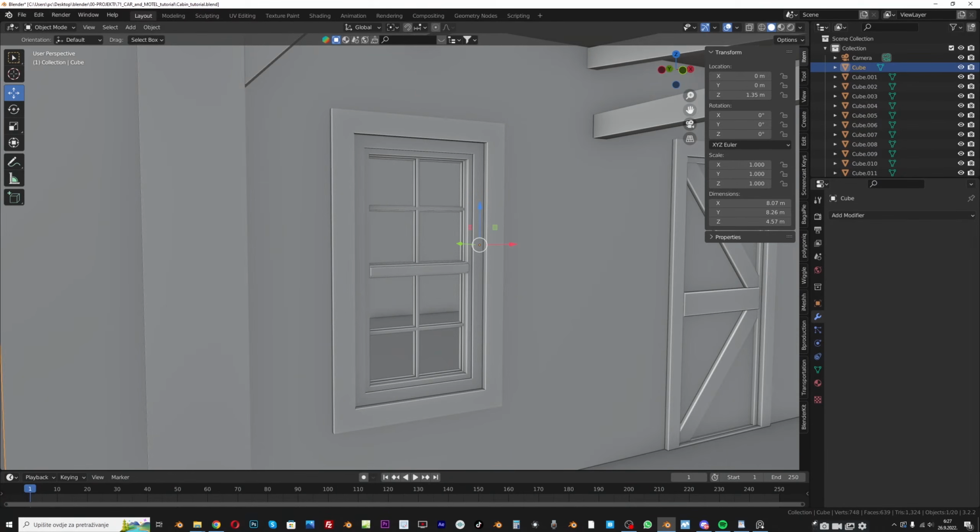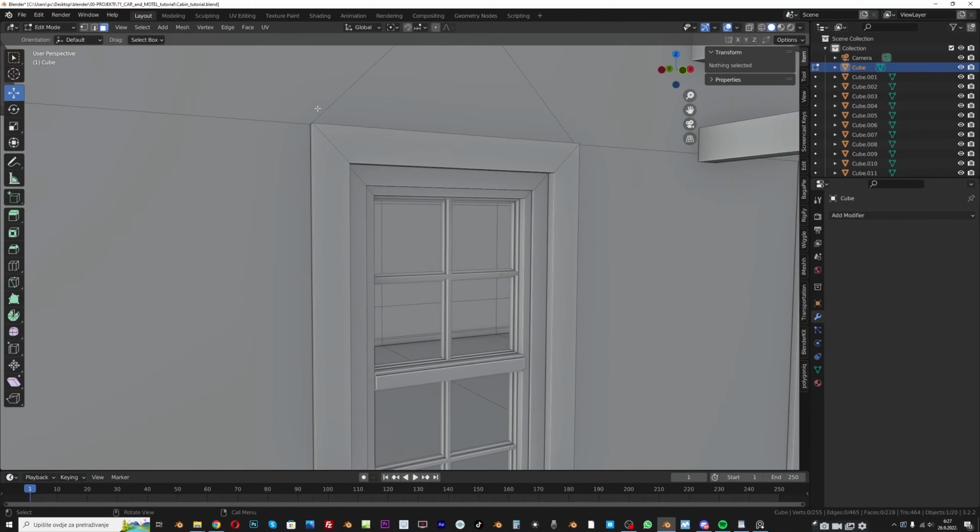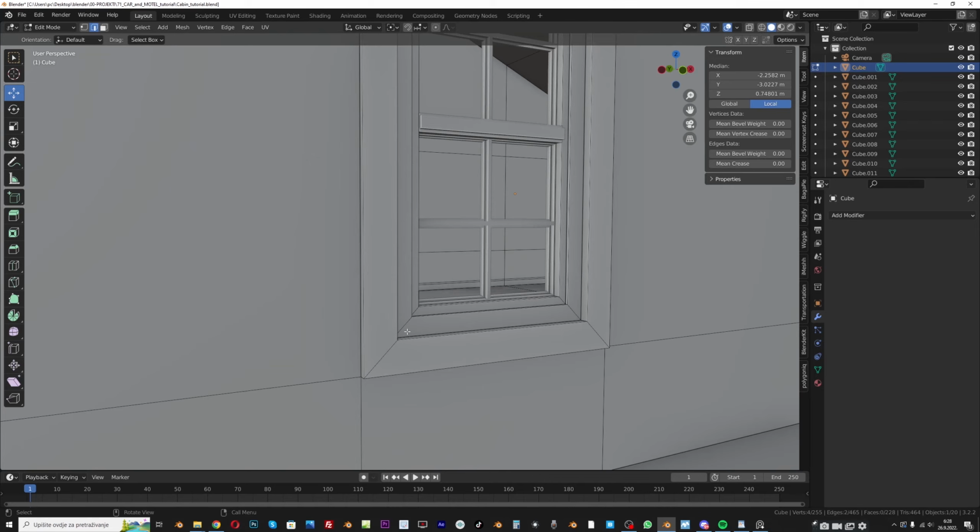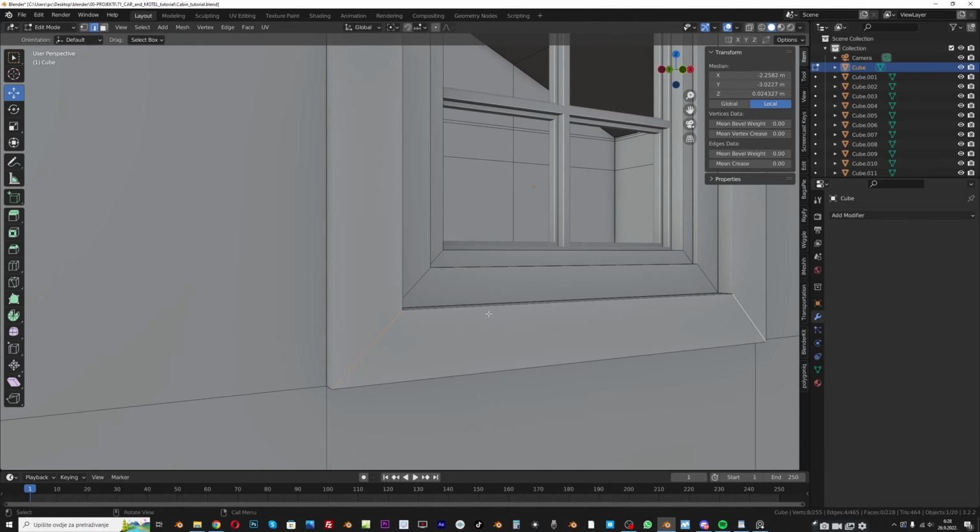And we can create seams here if we go to edit mode and grab these 4 edges. And now I will go with Ctrl B to bevel this. And if I scroll mouse up, I can add another loop cut here. And with Ctrl minus we can subtract selection. So if we go with Ctrl plus, we expand selection, and Ctrl minus is opposite. And now I have selected only this edge in the middle,